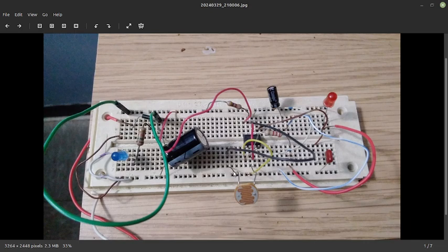You've got a photocell from pin 6 to 7, right? Pin 6 to 7 is the photocell. This is pin 7 here. This goes to pin 7, and this goes to pin 2 and 6. This wire joins pin 2 and pin 6 over here. The 4.7K I showed you all here, right?